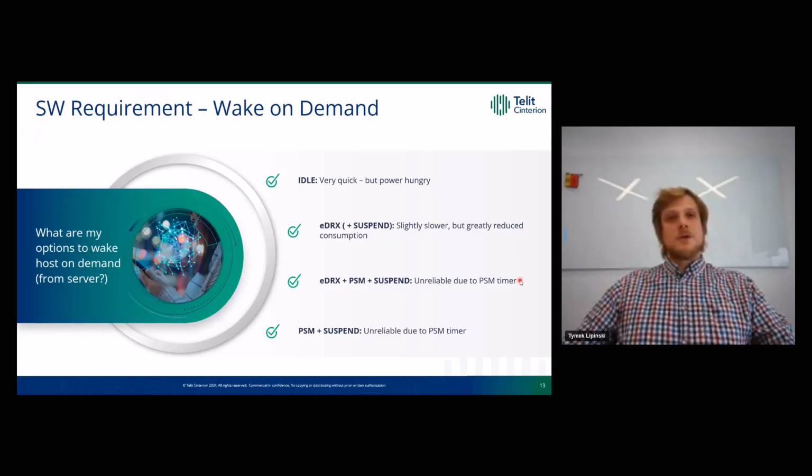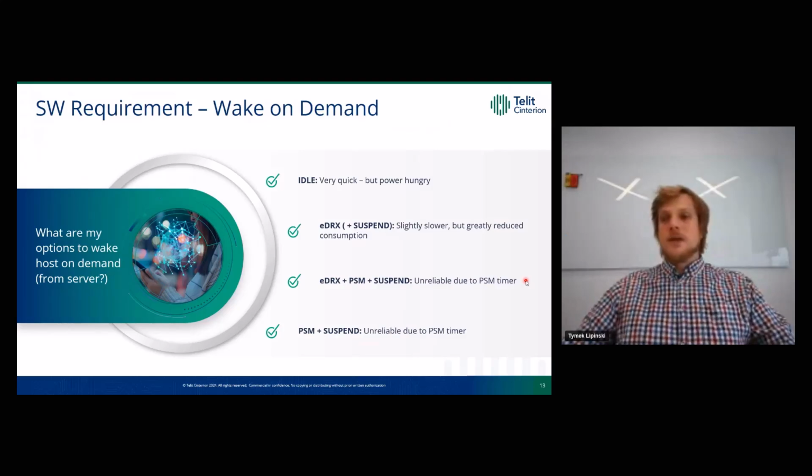So when we want to go into PSM, the modem, our application, requests the network, okay, I want to go to sleep for 24 hours. And the network may respond with, okay, you have been granted 24 hours of sleep, or the network may reply, no, I grant you 18 hours of sleep.